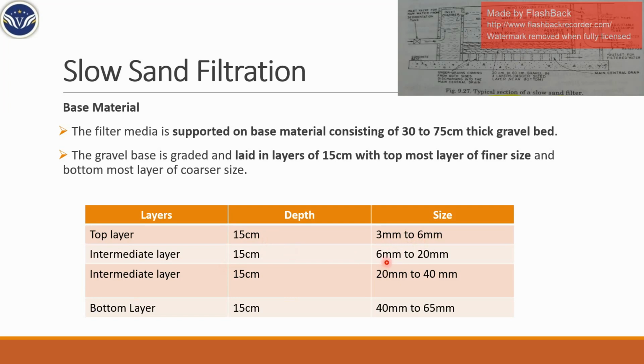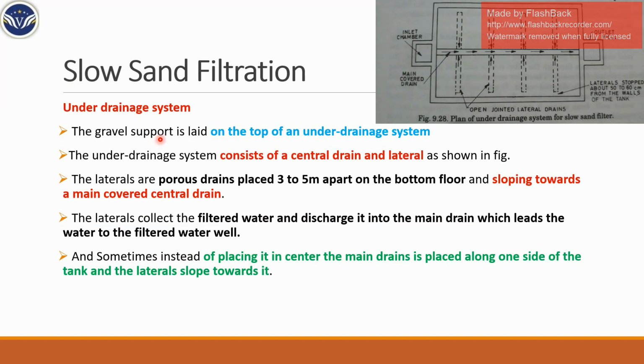Intermediate layers vary from 6 mm to 20 mm, again from 20 to 40 mm. At the bottom they are of bigger size. This size varies from 40 mm to 65 mm. So depth is around 15 centimeters. So this was about base material.